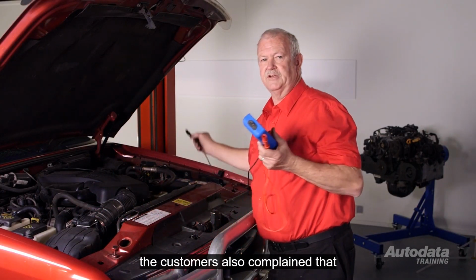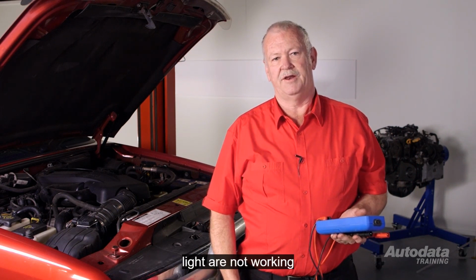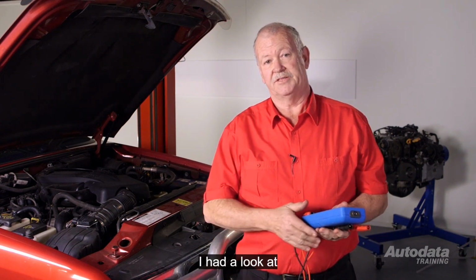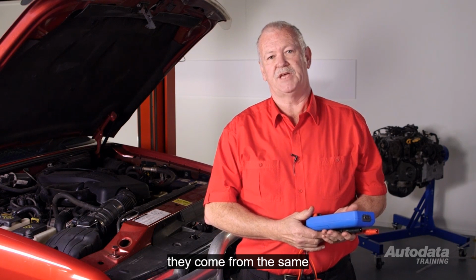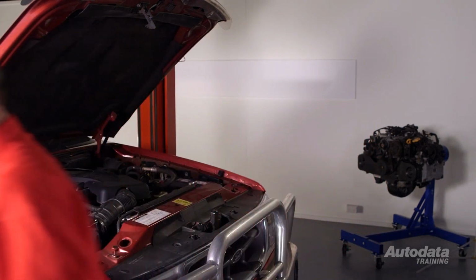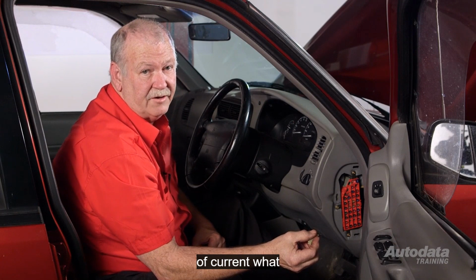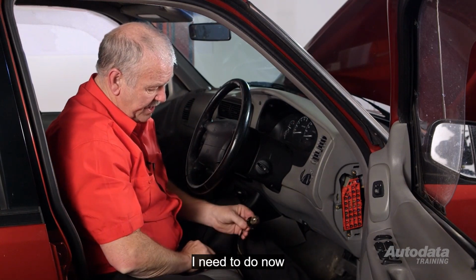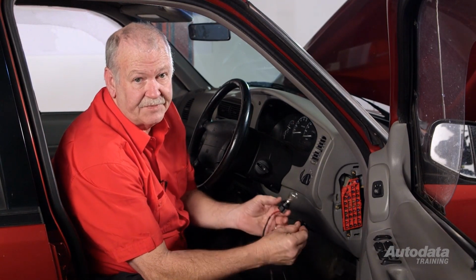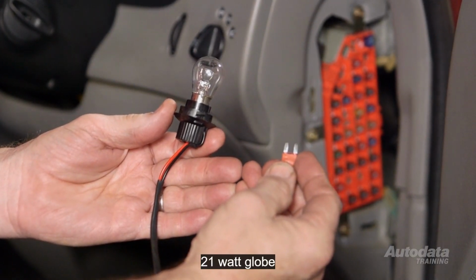The customers also complained that the right-hand front parking light and right-hand rear tail light are not working. I had a look at the schematic and found that they come from the same fuse. I'll now check to see if it's failed. The fuse is blown. That indicates an excess of current. What I need to do now is fit a test light. This one's made from a blown fuse and a 21 watt globe.